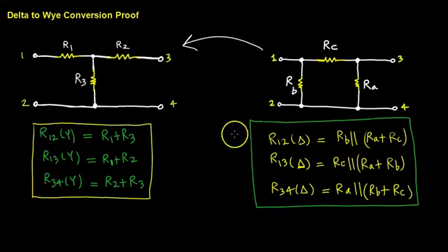So to do that, we have to think about something. The goal here is, remember, in the field of electrical engineering, what we most care about, when we're talking about blocks or modules or equivalent circuits, is how that circuit or model behaves at its terminals. So the key here is that if you want to convert this particular circuit, the delta, to a Y network, we need the IV characteristics or the equivalent resistance looking through any given terminal to be the same for both.